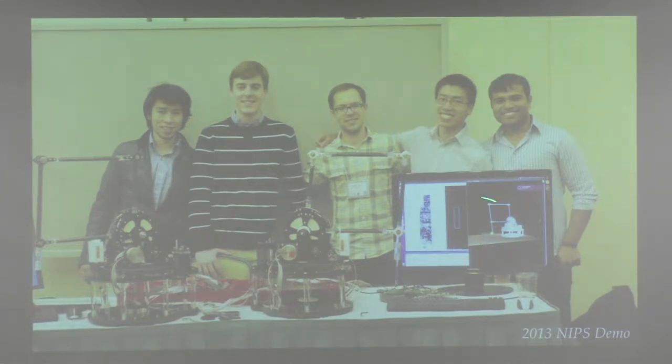And those three numbers would go to NeuroGrid. NeuroGrid is also getting the joint angles of these robots. They are 3 degrees of freedom robots that, through the computer, which is animating the robot to correspond to what's happening here, takes those 6 numbers and computes the torques that have to be driven to the 3 motors to move to that location. And so you move your mouse around and the robot will move.